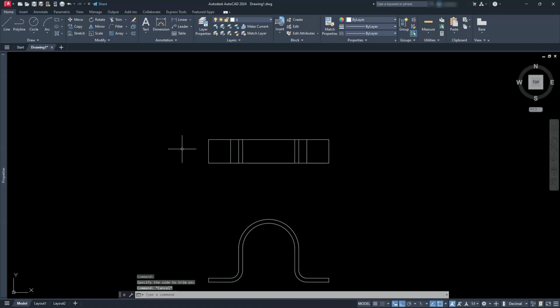All right, so now I have all of the lines that I need, right? Some of these lines are actually going to be hidden lines, and some of these other ones are kind of tangential lines. Now, normally we don't see some of the tangential lines when we're doing this in a 2D drawing. So I'm just going to go ahead and erase these two lines here. I really don't need them, but they will show up as tangential lines if you're doing any kind of 3D program or something along that line.